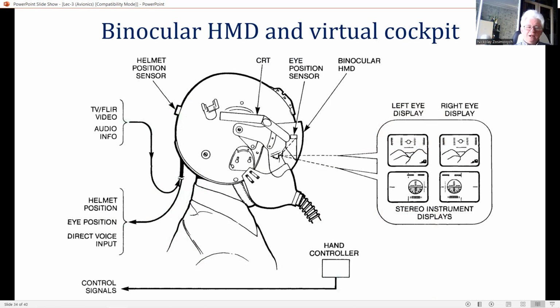When head up, the pilot views the outside world directly or indirectly by means of a TV display on the HMD from a head-steered gimbal electro-optical sensor, another, say, infrared imaging sensor or low light TV camera or CCD camera. When looking down at the instrument panel, the virtual cockpit computer system recognizes the pilot's head down sight line from the head tracker output and supplies this information to the display generation system.